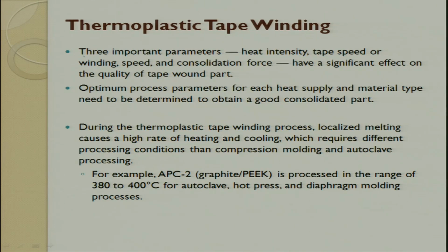So, the other three important parameters are heat intensity, tape speed or the winding speed, and consolidation force. These are the three important parameters: heat intensity, tape speed and consolidation force. These three parameters have to be optimized such that you get the best out of this process.